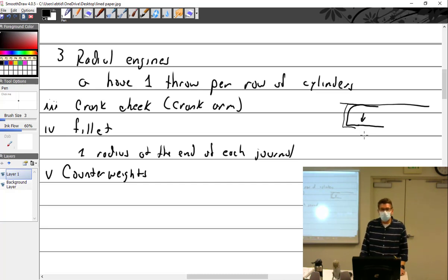So when you're putting them together, you have to pay a lot of attention because the way they change the order usually is the size of the pins that go in those holes. So the bushings are all the same size, and on the crank, oh boy, did I hate changing bushings on crankshafts because they're really pressed in hard, and you just feel like you'd break one of those hanger blades, which is the part that comes out where all the bushings go in. Anyway, you gotta be careful because if you get the wrong rollers in the wrong hole, then you've upset the dynamic balance. The only way to fix that is to take it apart, but I assume the only way you're going to find out is because the crankshaft breaks, and so that would be really bad.